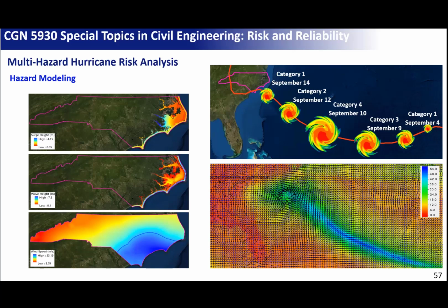a fragility curve like this, this is the wind fragility, and this is 31 meters per second, and this is 50 meters per second. So if you have 31 meters per second on a community, how much damage will you have? It's 0, right? So what we did, we isolated the buildings that are vulnerable to wind speed that doesn't cause damage. So this line is going to say that this part of North Carolina is going to have wind damage, but this part is not going to have wind damage